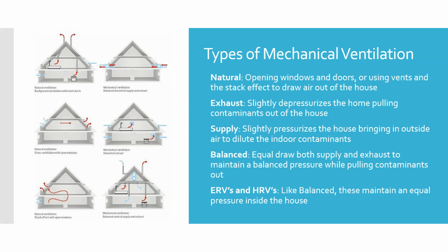It's often included with a filter to filter the clean air, or it's pushed into the return plenum. It's better suited for hot, humid, or mixed climates like DFW and east and then the southeast part of the country. It may bring in pollutants and humidity and require appropriate filtering and dehumidification systems. This is what we're fighting in Texas: it's pulling in humidity, and now you have to turn around and dehumidify because it's adding humidity into the home.